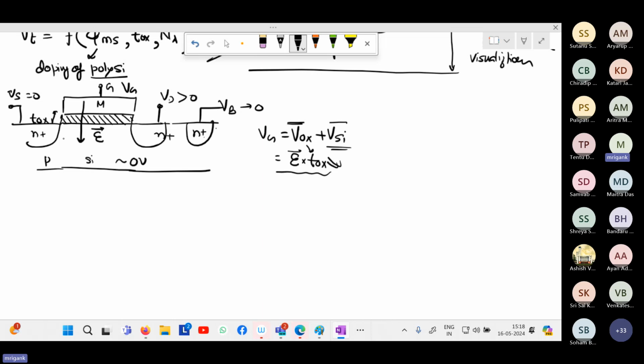Generally the p-type silicon will have holes all around. The uniform hole density will be there, which will be dependent upon approximately the acceptor concentration. So if you have concentration Na equal to around 10 to the power of 15 per centimeter cube, you will have that many holes in that piece of silicon, depending on the dimension and the doping concentration. Now, when you apply a positive potential, the holes are supposed to be pushed down. They will be pushed away, right? So all the holes will go down, and the minority electrons will be accumulating near the channel. And as a result, the channel formation takes place.